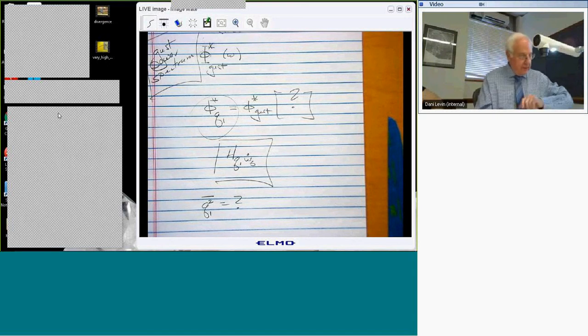Okay. So we have an equation of motion. We've included the effects of the motion on the aerodynamics, at least within the framework of piston theory. We've included the effect of the gust, otherwise we can't do a gust analysis. If the gust is represented by something simple like a step function, we just integrate it. Actually, in this case, you could probably integrate it analytically, but you can certainly do it with the computer, right?